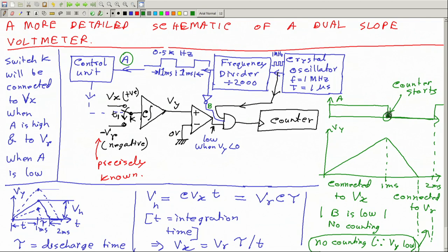Okay. So how can you do that? There are many possibilities. You can possibly take a reset input, and you see, this is a moment where we have a falling edge of this signal A. So we can take a negative edge triggered reset based counter, and then you can connect this.